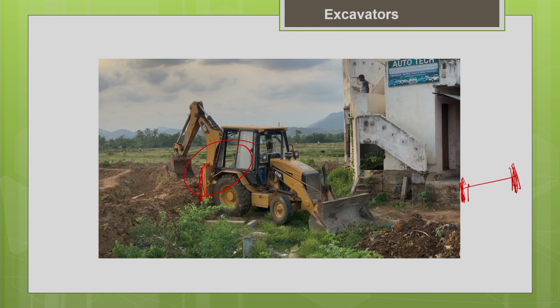This is because the machine is wheel mounted. So when the backhoe is doing the excavation job, you extend the outriggers completely and transfer the load to the ground through the outriggers, instead of the wheels. This will ensure the stability of the machine when it is doing the excavation. Now you can see this video of how the trenching operation is done with this loader backhoe combination.